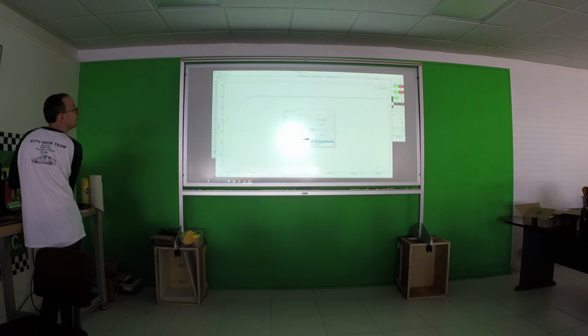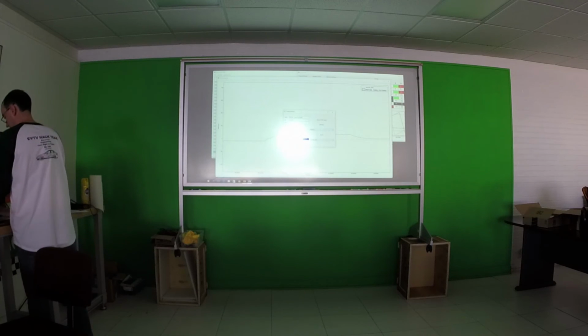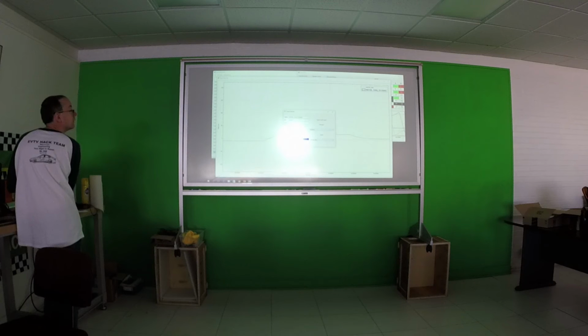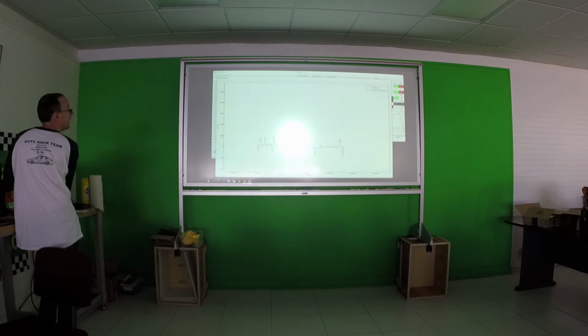And add here another graph, motor torque, probably out there somewhere. Motor torque is unfortunately nowhere near the scale of RPM, but what we can do is select motor torque filtered here, edit the selected graph. Let's say instead of that, we'll do a scale of 10. Now that's a little nicer. You can click on the axes here and scroll just one axis at a time, scale it, scroll it around, click this one, widen that out, and now you can see a graph of motor RPM versus torque.